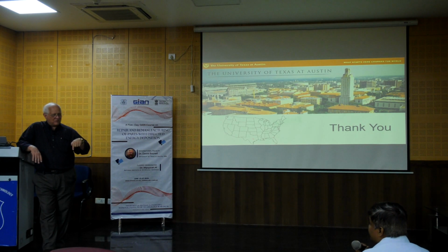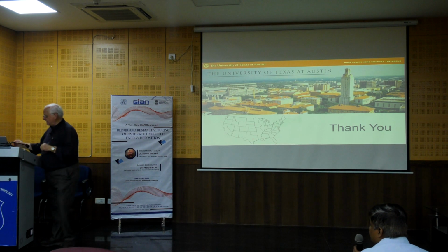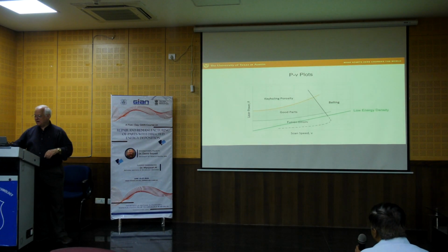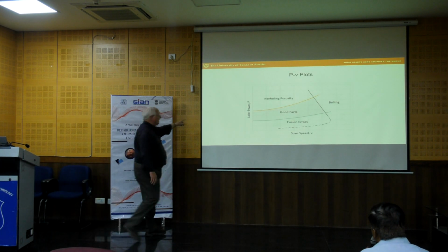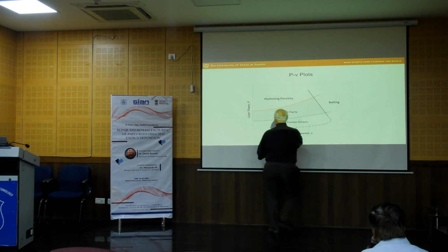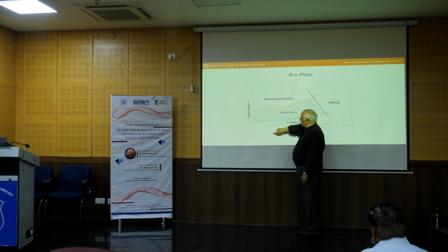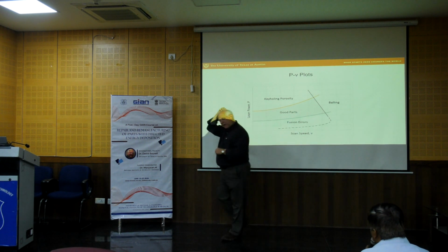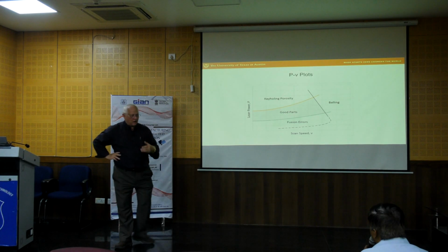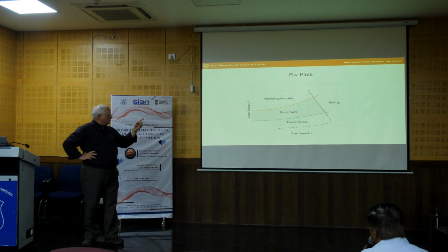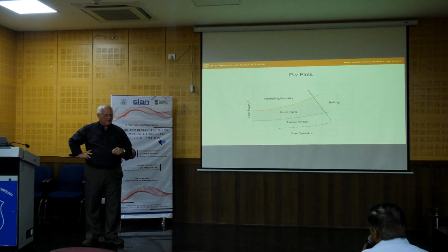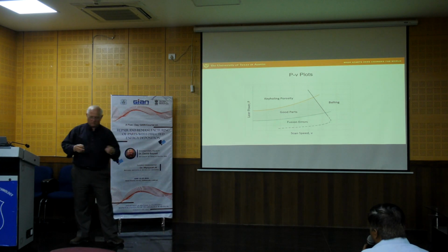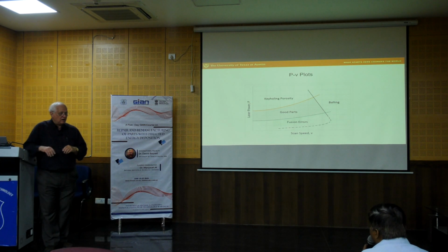We go from a low power to a high power, which effectively cuts across this plot, right along here. So it cuts across here, so we can see the entire span of the process, and we're reasonably sure that we'll hit the good spot, the good part area. So we do that run, then we inspect the parts, do microscopy or tension testing, whatever we need to do on the parts.